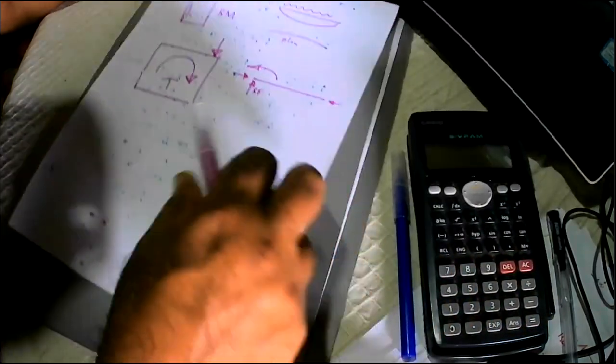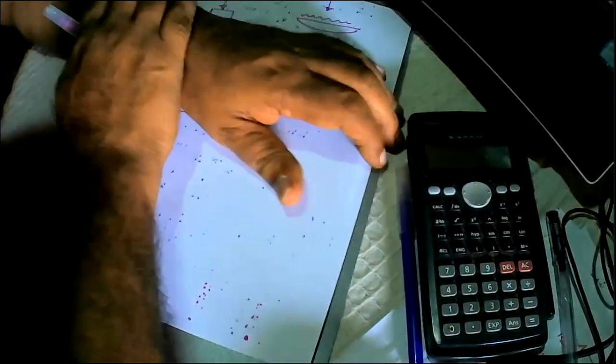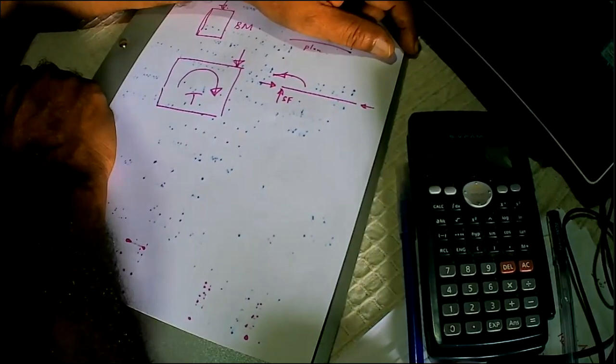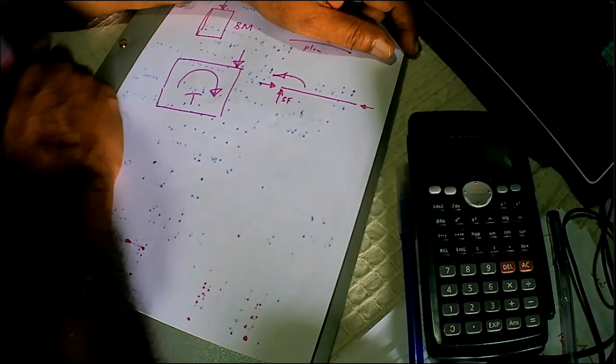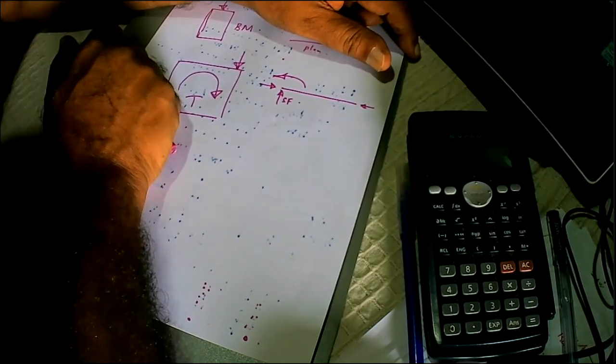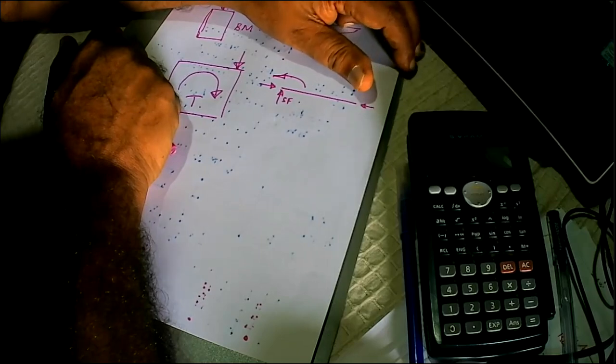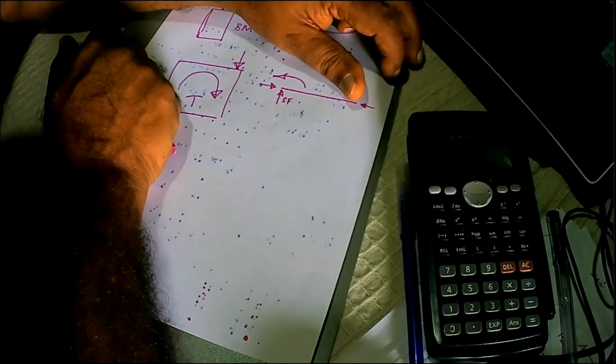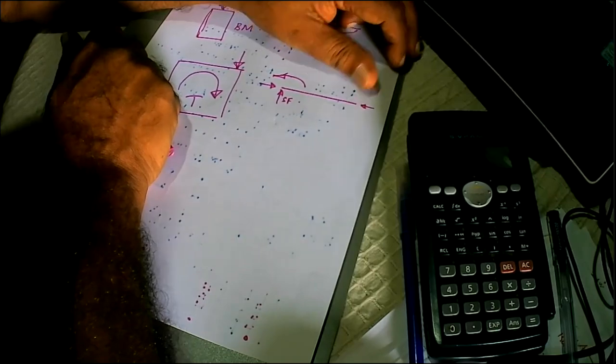That's the type of behavior that you get with rigid diaphragm behavior. So basically, when you are doing 3D modeling of a building, you have to keep in mind that every element will have so many degrees of freedom, but out of all this, for our design purposes, we use only the most important or dominating behaviors.